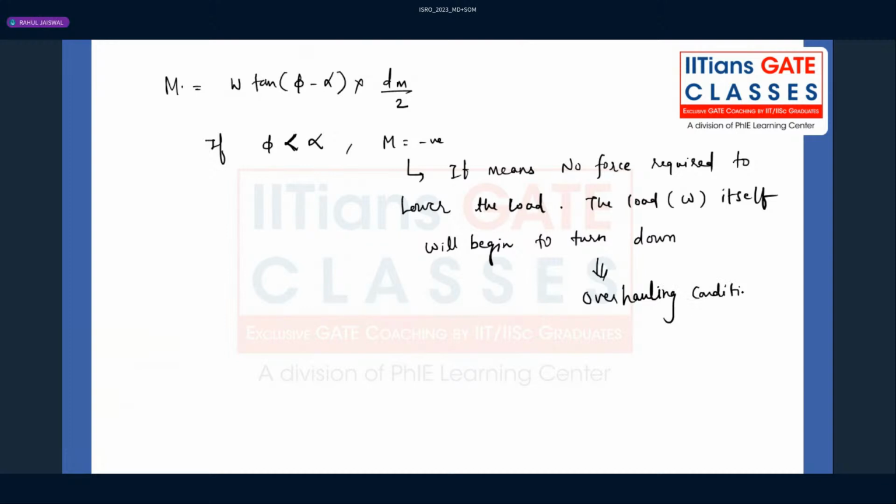And for any screw thread design, for a screw jack, it is not at all advisable. This is not a very favorable condition. This is also called back driving of the screw. So this is not useful in screw jack application. Make a note of it.